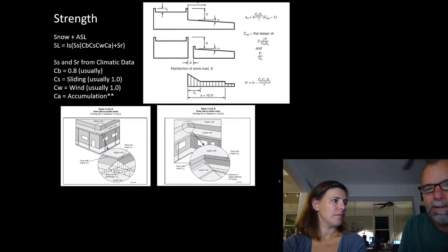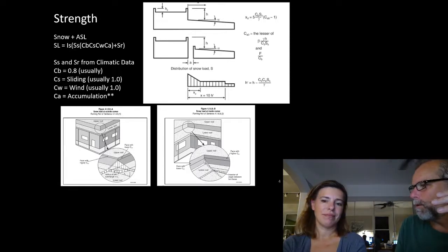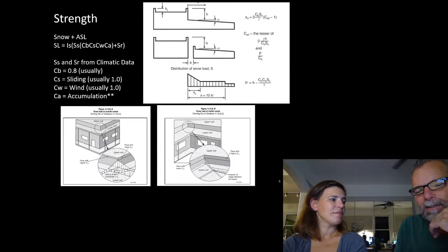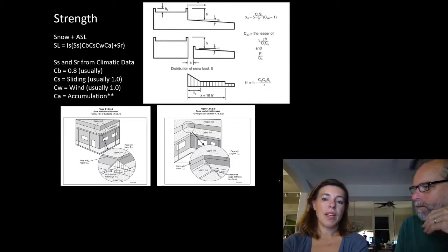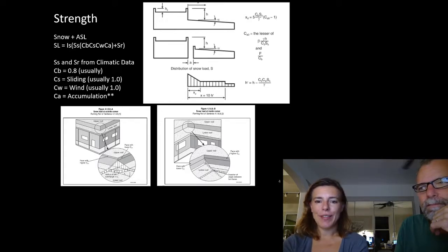snow when it just falls, we're designing canopies, like just a little canopy over the doorway on a building. We're designing it for 3 meters of snow. And that's what the building code requires of us. 3 meters of light fluffy snow, or a whole meter of dense packed snow. Really high loads, but we're talking about 1 in 50-year storms.